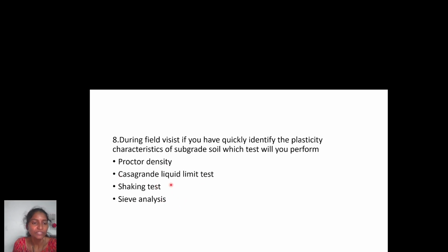But if you see the shaking test, if you remember, you can hold the material in your palm and try to dab it, then you can see the amount of moisture that is getting separated or segregated. So the shaking test is the one which we usually do in the field visits.